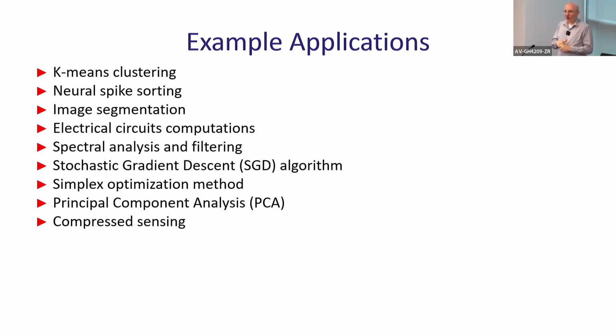But people came up with the question: can we reconstruct other signals with faster ripples, if we do not sample them with an equal sampling rate, but with more adjusted and adaptive rates? So we will sample maybe more points where it's fast and fewer points where it's slow. We'll have exactly the same number of sampled points, but we'll be able to reconstruct higher frequencies somehow. It's kind of smart sampling. So this is that compressed sensing type of sampling idea, where you can take not every point, but particular points at particular times based on how the signal looks in time, and you will store only those particular points instead of sampling on the clock.